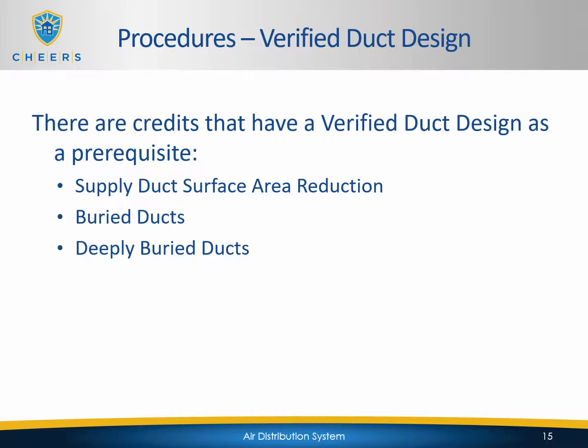Now, there are also credits that have to have verified duct design as a prerequisite. So supplied duct surface area reduction, buried ducts, or deeply buried ducts. So if any of those three credits show up on the CF1R, the verified duct design is also an additional requirement. It will be listed on there, but this is just as a heads up. The verified duct design is a prerequisite of these three additional tests.